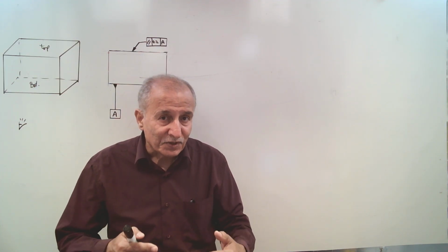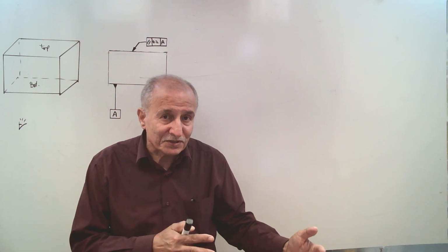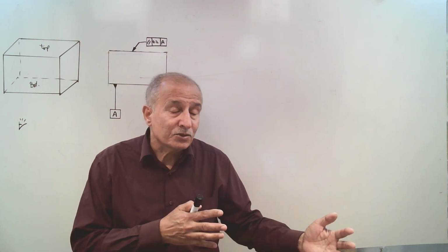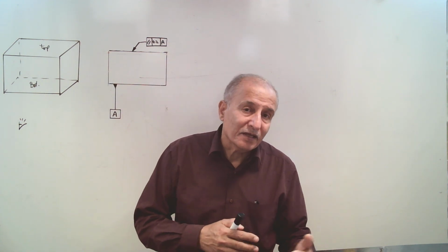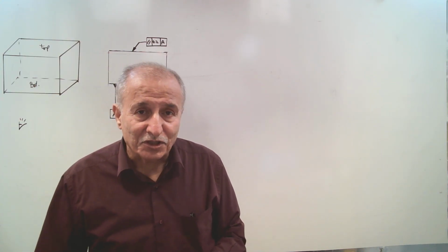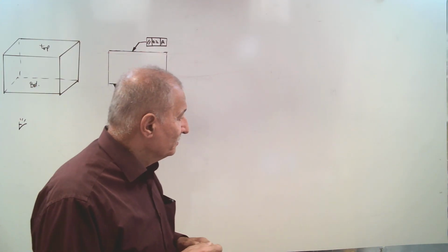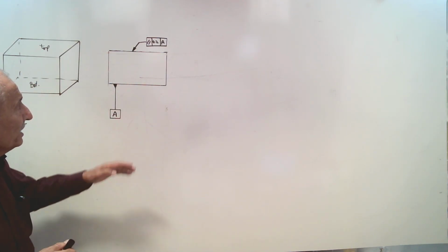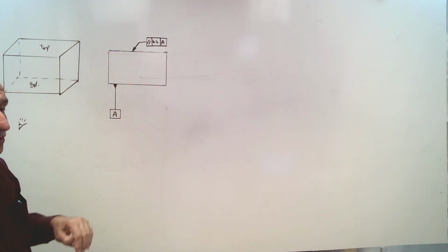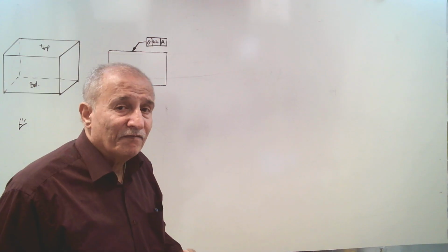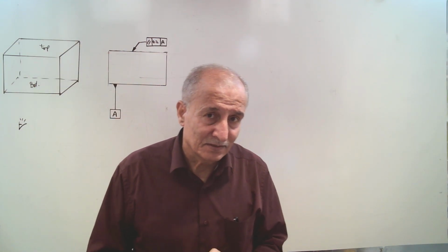They are expecting us to complete our sentences. The surface is parallel to datum A. Then an orientation control needs a datum. And this parallelism indirectly controls flatness as well.